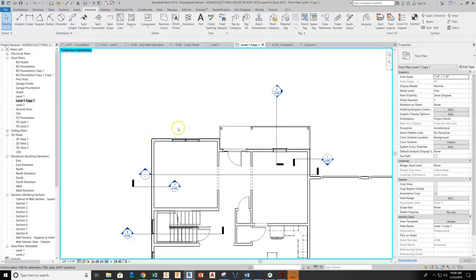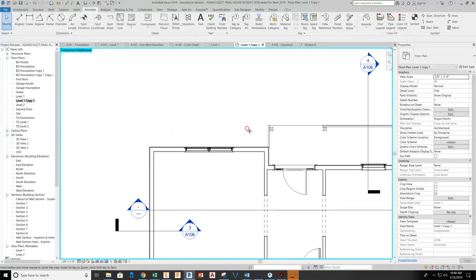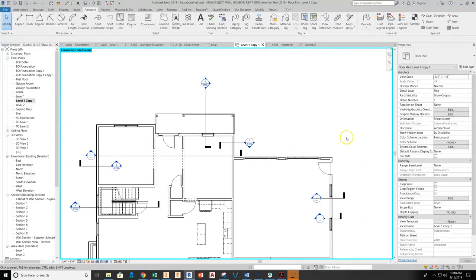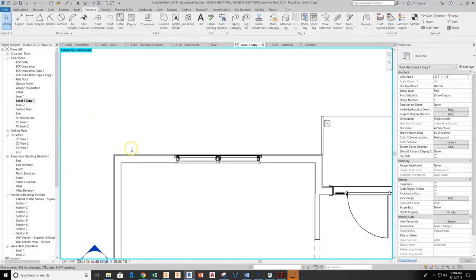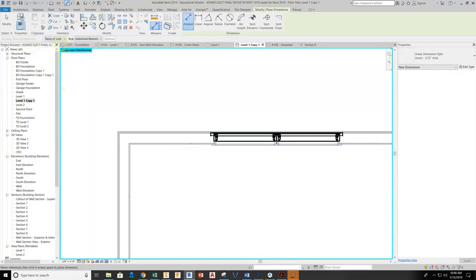Okay, in this video we're going to walk through how to get some dimensions set up on a Revit drawing and how to properly pull and organize your notation. So we're going to go ahead and zoom in on this outside corner of this structure. I'm going to grab my Align Dimension tool, and I want to make sure that this is set up to face of core.